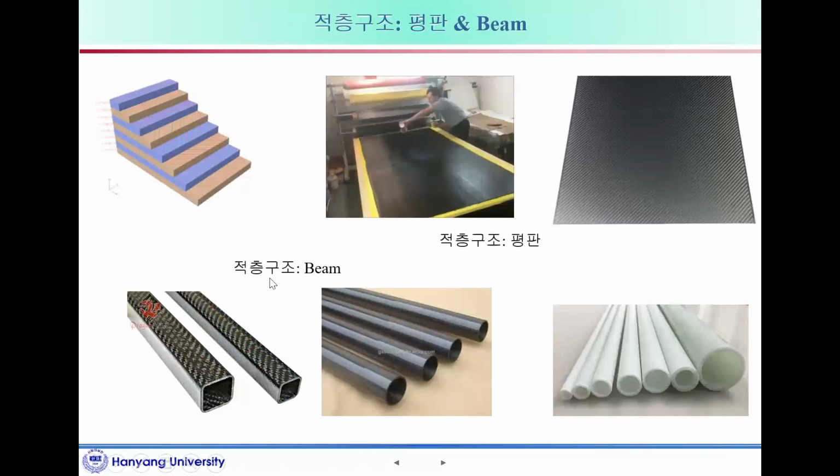Another one we would like to cover is the 3D beam, which is mainly for beam structures. Say we have a beam. This kind of composite beam is usually made by pultrusion. Pultrusion has a uniform cross section and is pulled, and you can have many different fiber angles and materials. You can have certain sections, sometimes closed, like what we call a box beam or a tube with a circular cross section.